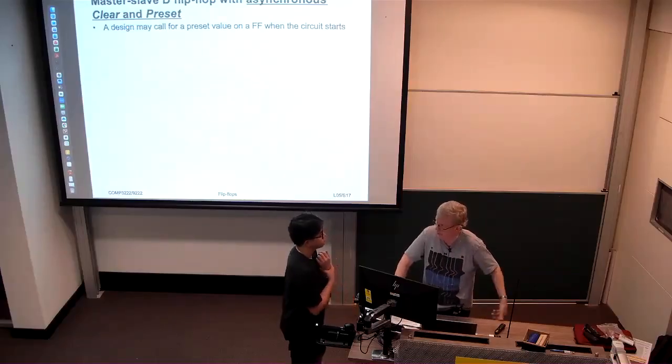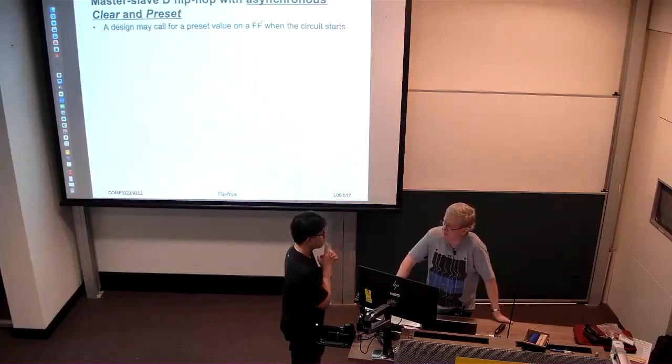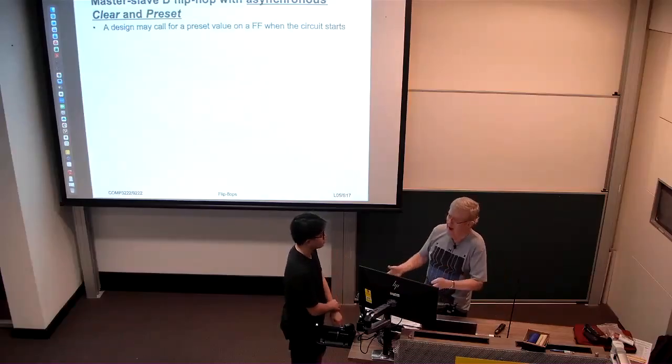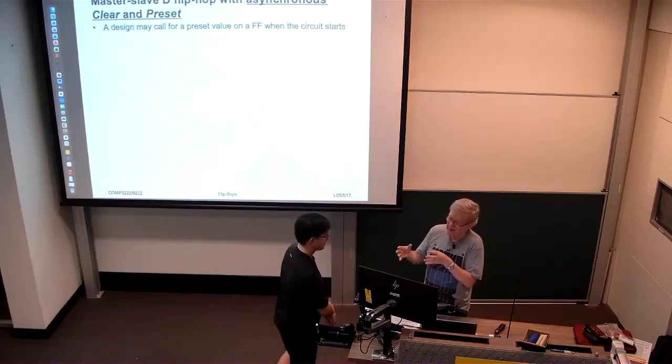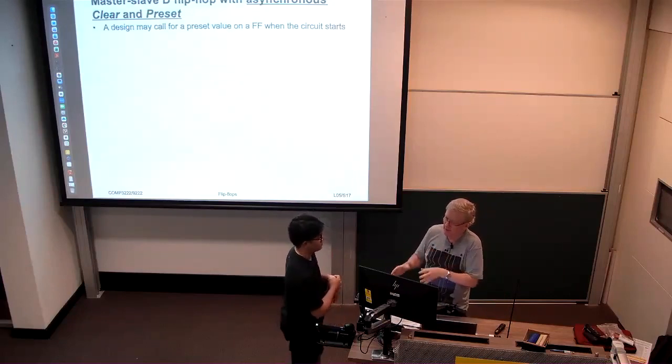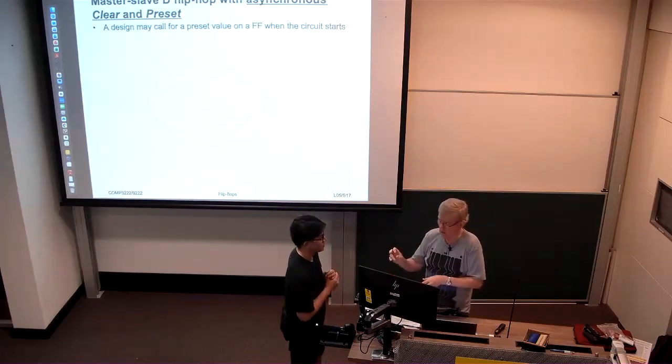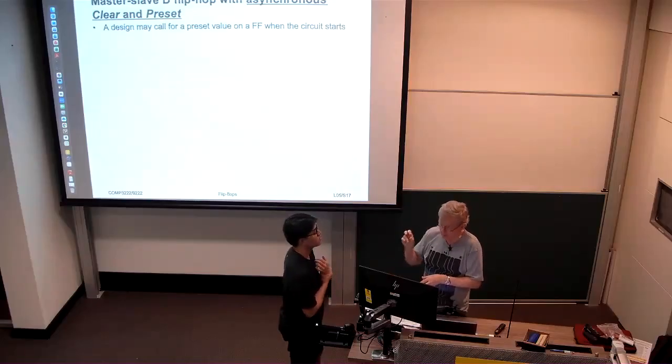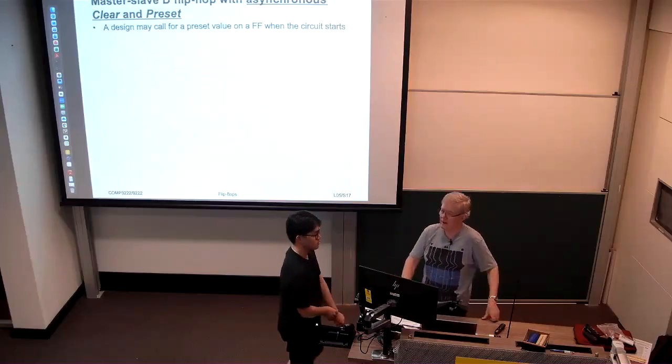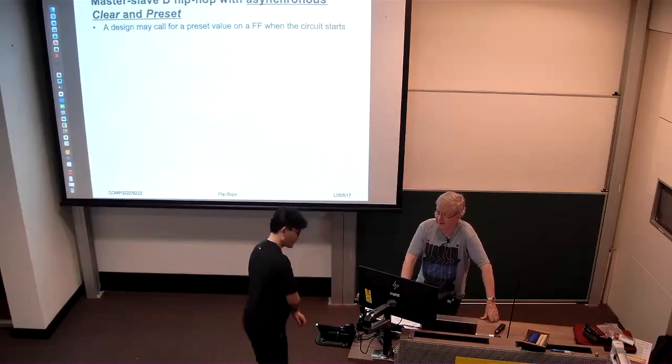But don't we have the condition for when the clock? You do, but you don't want to trigger it then. Again, it's an idiomatic thing that if you want to specify a flip-flop, for a synchronous design, only the clock goes in the sensitivity list. Okay?